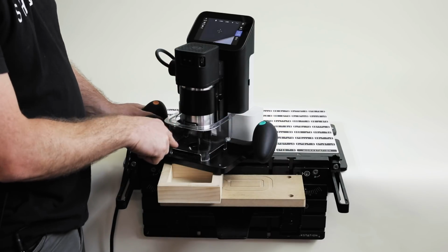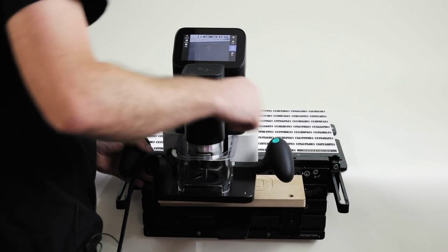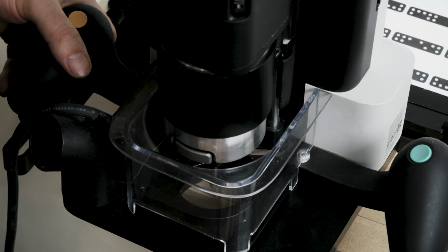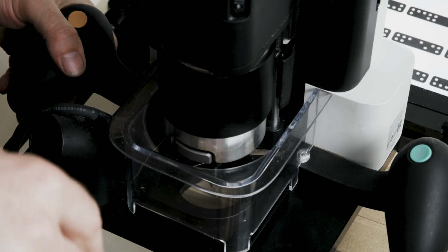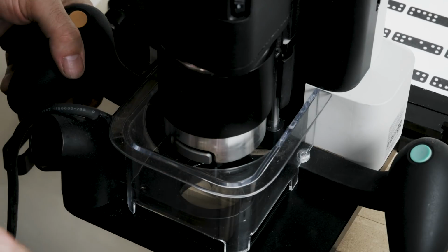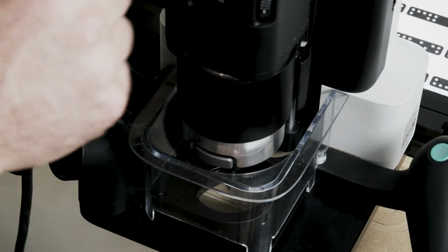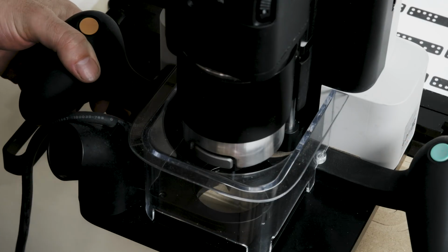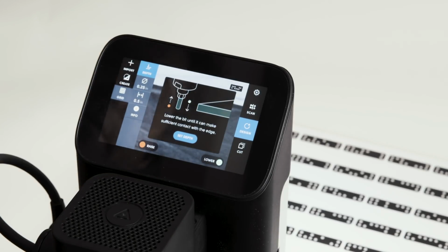Right, so I've got the cutter with the point facing down here. I'm going to come over. Now the cool thing here is we actually have a cylindrical shank if we just go a little deeper than the cutter point itself. So I'll be using that for the first two physical probes, and then for the visual probe I'm going to raise up midway through and show you how to visually probe as well. We'll bring the cutter out beyond the edge. We don't want to mar our stock, and then go same as we have previously, new grid.